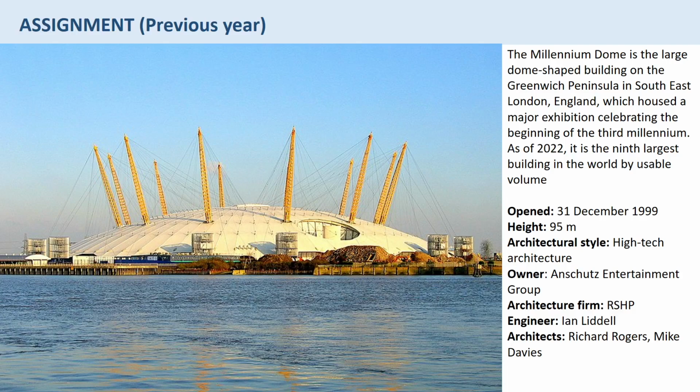A diagrid, which is a portmanteau of diagonal grid, is a framework of diagonally intersecting metal, concrete or wooden beams that is used in the construction of buildings and roofs. It requires less structural steel than a conventional steel frame. The Hearst Tower in New York, which was designed by Norman Foster, uses 21% less steel than a standard design. The diagrid obviates the need for columns and can be used to make large column-free expanses of roofing.